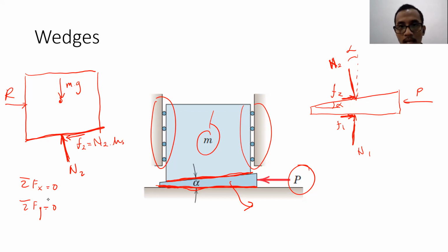Because the condition at the beginning is stationary and it's supposed to be starting to move. So what is the minimum force, given there as P, in order to ensure that the wedge can go in? If at the beginning it is stationary, then we have to make sure that the force can handle the maximum friction force. Correct or not, Azhar? Yes, that's the logic behind it.